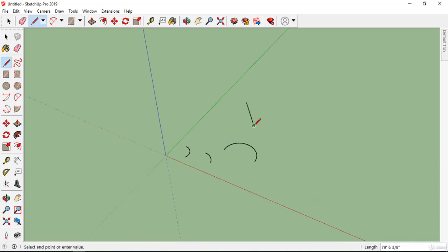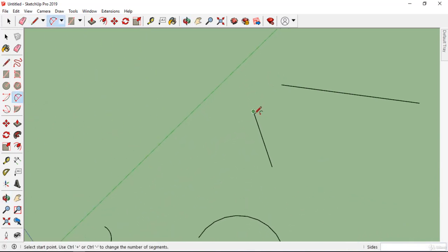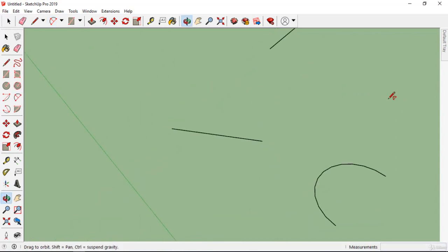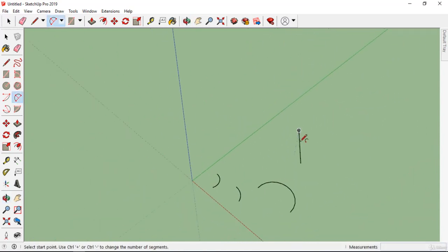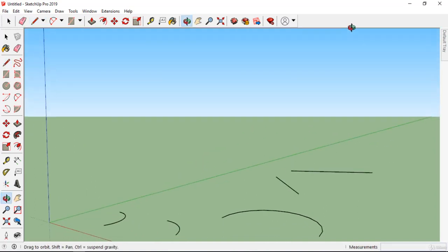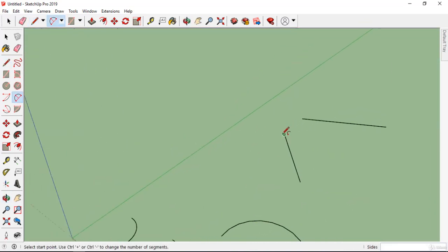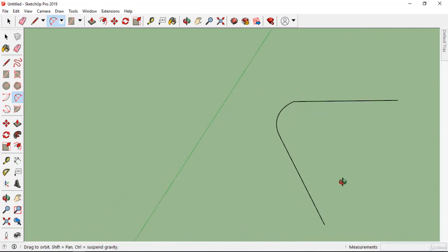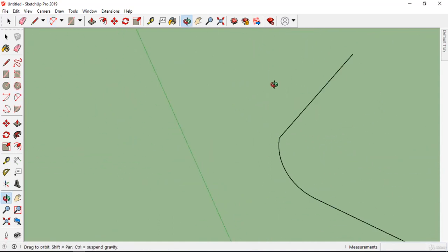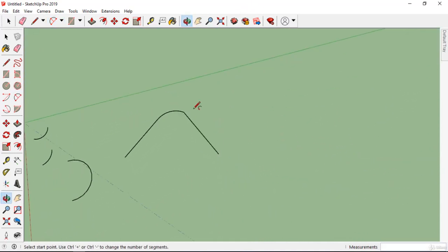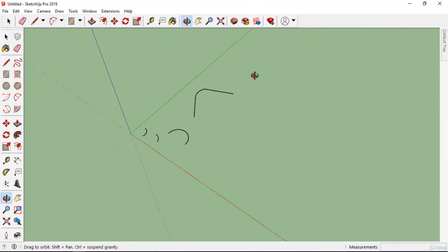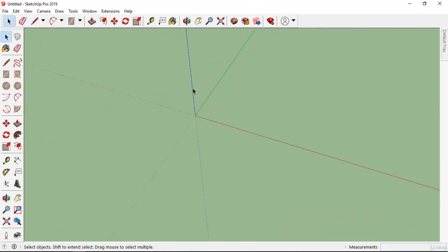It's really simple. If I have two particular lines and I want to join them by an arc, I directly select them. Sorry, these two lines are not in a single plane, so I will make these two lines be in a single plane. Now I will join them with this 2-point arc. You can see the blue line depicts the perfect arc that can join them, and I double click, and I have this arc to join these two lines. It's quite helpful here also. I request you to learn this and try it by yourself.